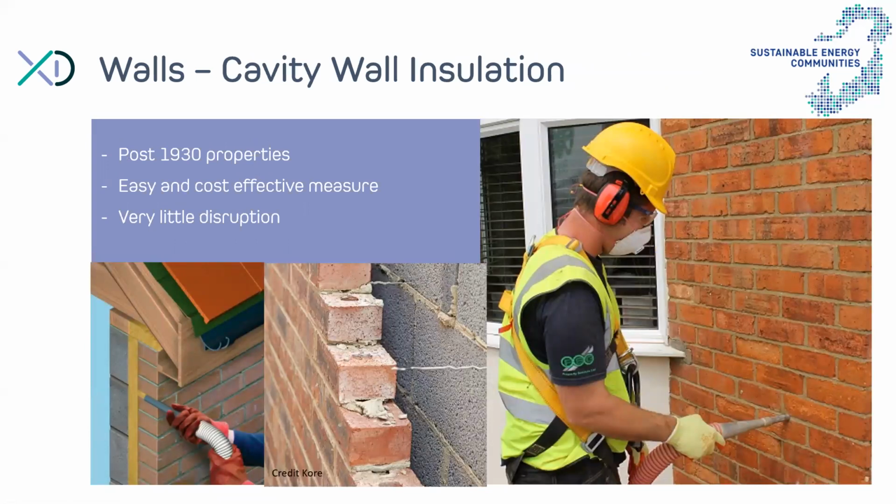Cavity wall insulation. So until maybe the 30s, most walls would have been built as, let's say, solid brick or solid stone walls. But from that period on, cavity walls started to appear, initially in brick walls, but eventually with the advent of concrete blocks, we've seen many houses built with a cavity in Ireland, with either two concrete blocks, one inside, one outside, or concrete block inside, and then a brick layer on the outside. And the function of that cavity is to allow for any kind of rain penetration or moisture penetration to drain down through the cavity.